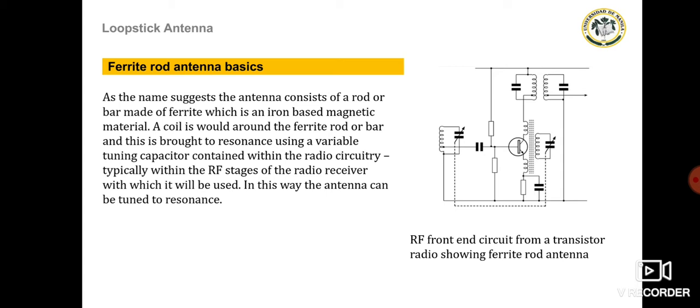The inductor assembly linking the emitter and collector forms this. The tuning capacitor is mechanically linked or ganged with the RF antenna ferrite rod tuning. Finally, the signal reaches the IF transformer and enters the intermediate frequency or IF chain.